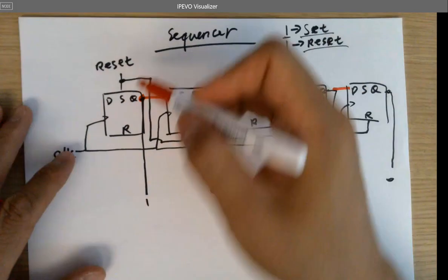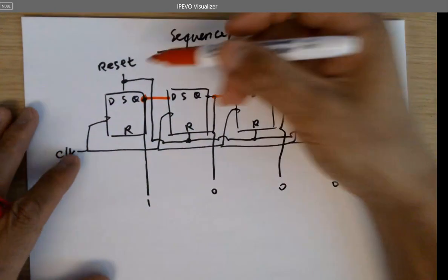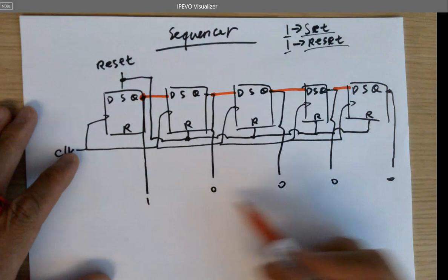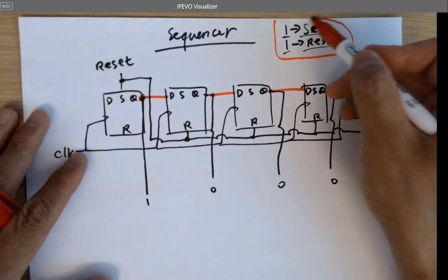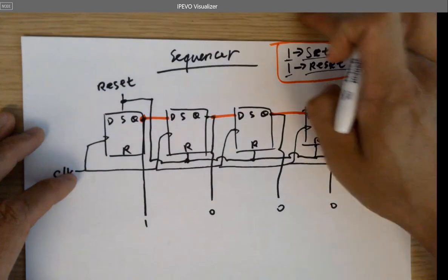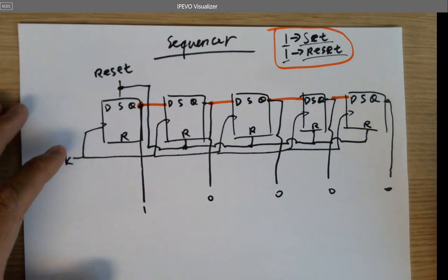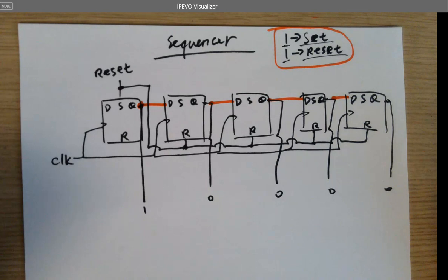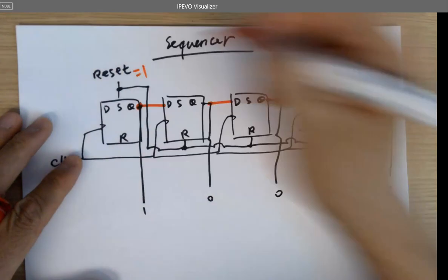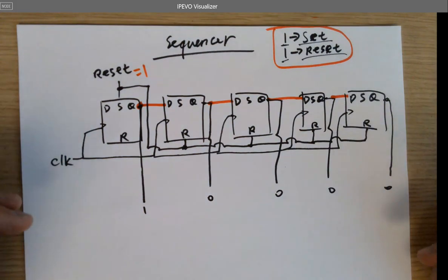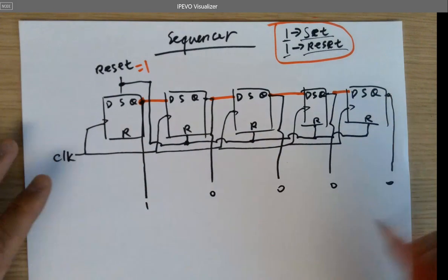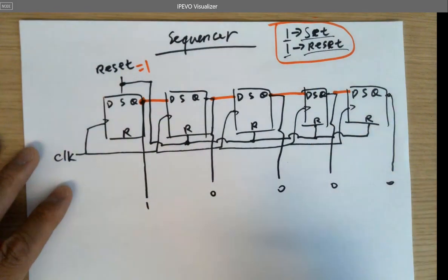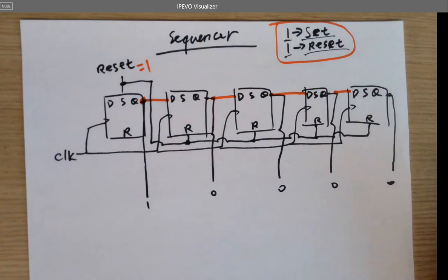You want to give what kind of signal to this line to make this happen? You want to give a what to that line to make it happen? Yeah. At the very beginning, just give a 1. Okay, so you need to design the control logic to give a 1 at the very beginning to reset the entire SAR ADC, the SAR logic.